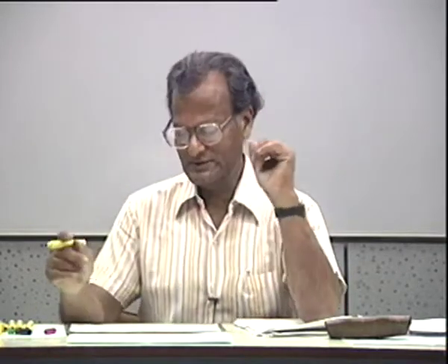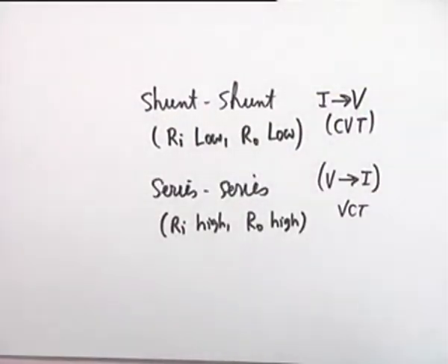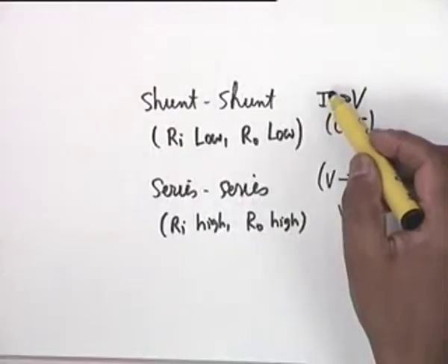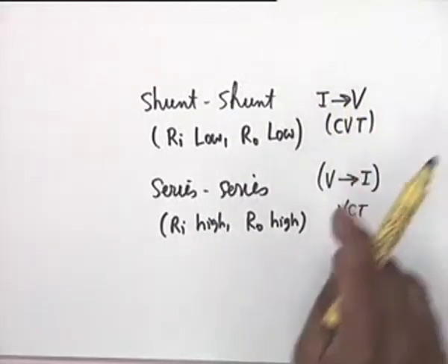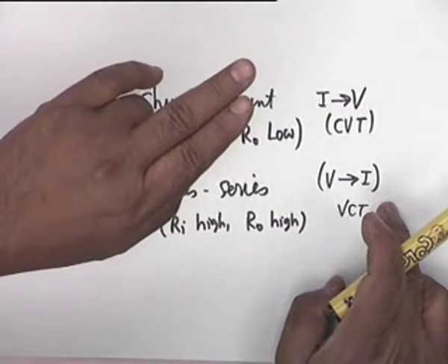But what would be your choice? Suppose I cascade shunt, then series. What would it be used for? Current amplification. Because in shunt, the input is a current, and then if you use a series, the output is a current. So it is a current to current.